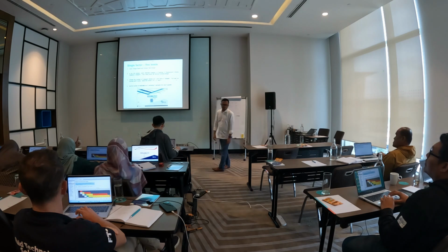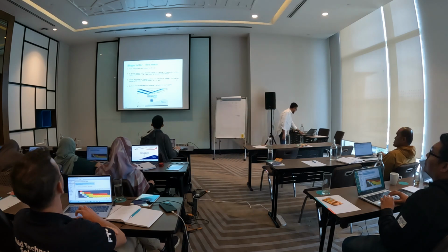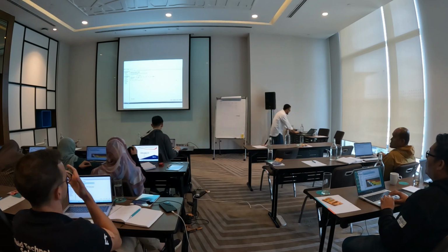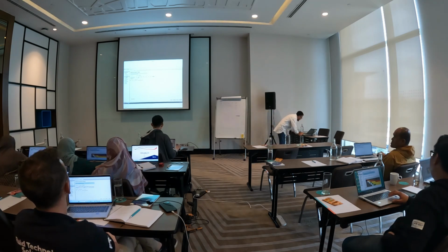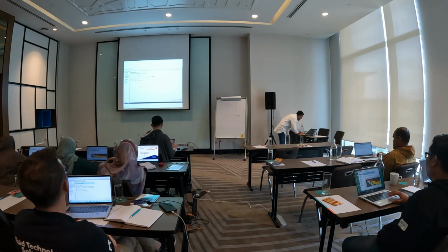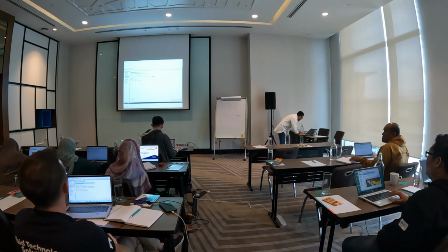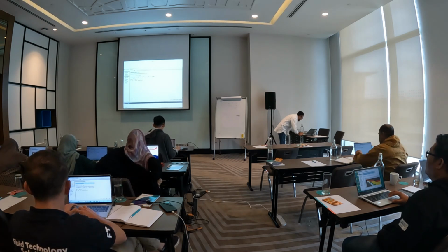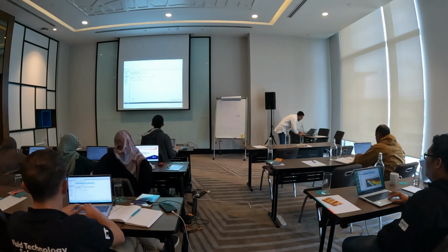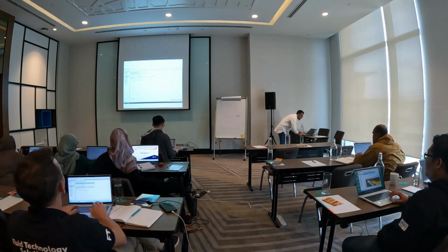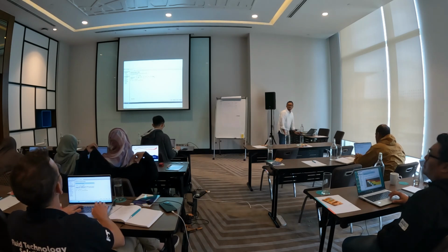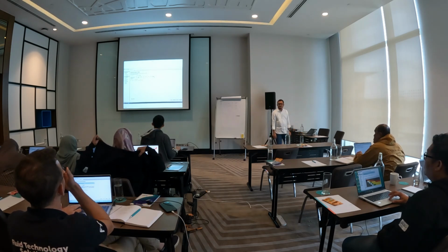This is also known as general factorial design. So you select multi-level category, and then you fill in the name Supplier, and put the nominal type with 5 levels, because we have 5 suppliers, and then put A, B, C, D, E as the levels.